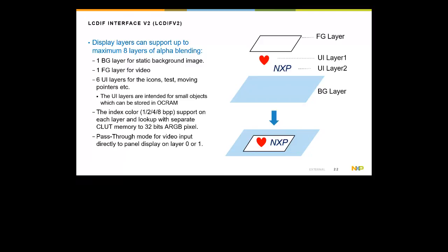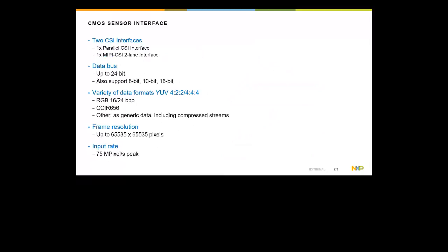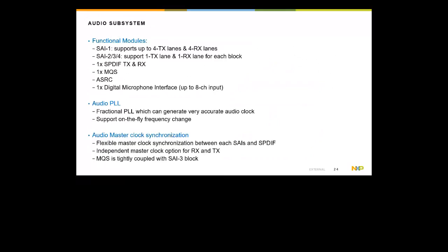That being said, we do still have our typical CMOS sensor interfaces, as I mentioned before, that support a variety of formats, and we're always improving the formats we support, as well as the resolution and input rates. And then finally, to finish it off, the device also includes an audio subsystem for some of those voice and audio applications that I discussed previously. It supports your typical SAI and SPDIF interfaces, but it even includes a digital microphone interface, which allows you to connect directly to PDM microphones.